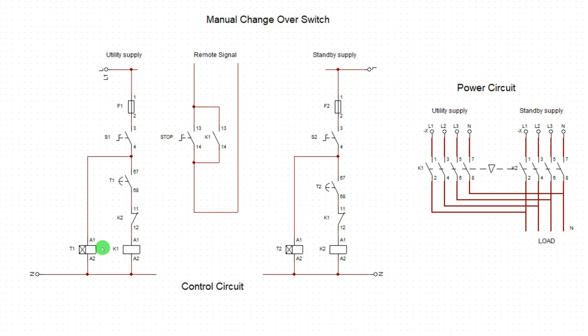Sorry. We are going to interface another relay that will send power to this contactor so that the fragileness of this will be overridden. So let's do that. How are we going to do that? Let me do that. Watch me do that. Take away this, or rather we can insert an ordinary relay here.